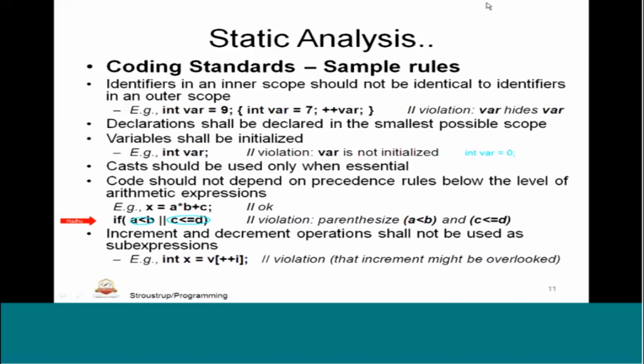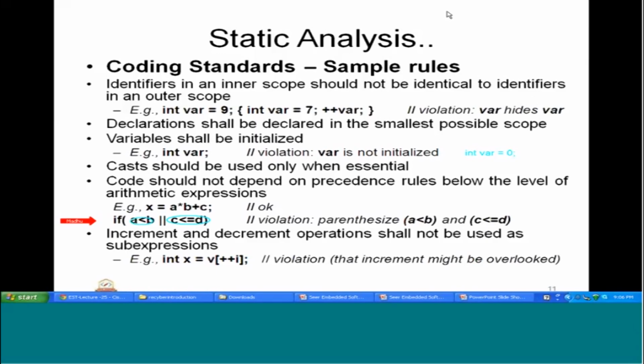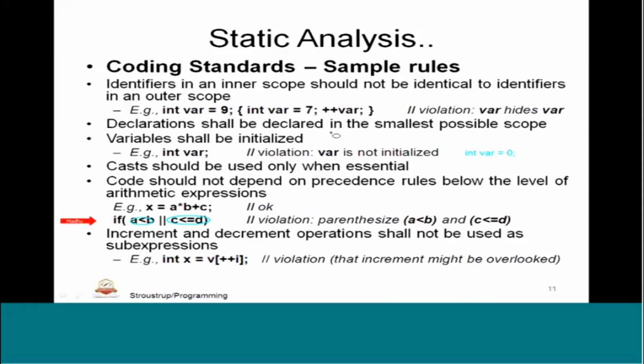Some of the compilers would not have the precedence defined by default, so it may take a different way. To safeguard against those issues, it is definitely better to have precedence taken care of in the program. So that needs to be analyzed appropriately. These are typical issues that I have seen in the embedded industry; precedence rules have to be followed appropriately. This is especially useful in arithmetic expressions as well as logical expressions.